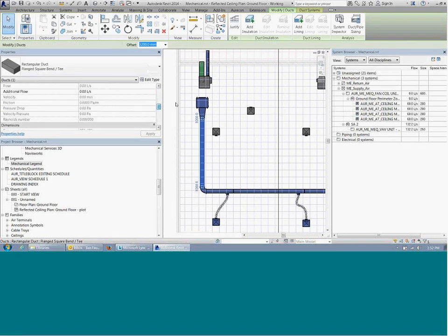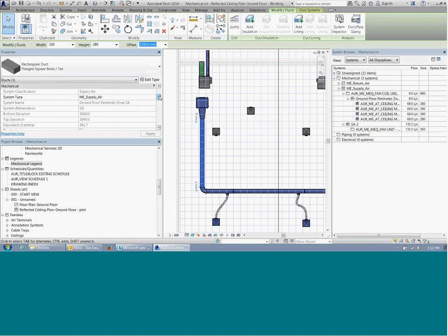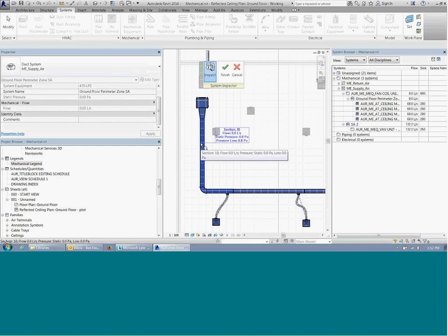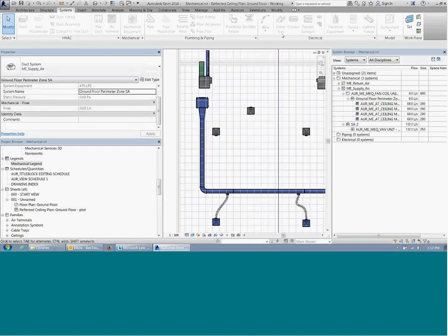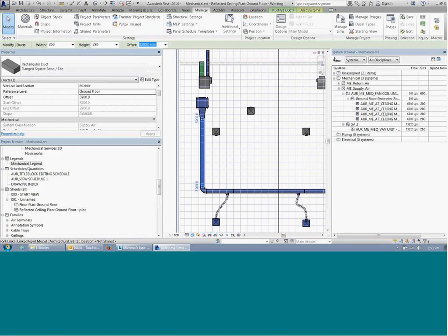You may go, yeah, we want it to be a certain way through, but all of a sudden you've got a space issue, so you've got to change the ducts. Instead of being square, you might have to turn it into a rectangle, but have the same size airflow through it. So as you're drawing it, the duct might change on the visual side. It might not work if you don't keep the airflow all the way through, correct?